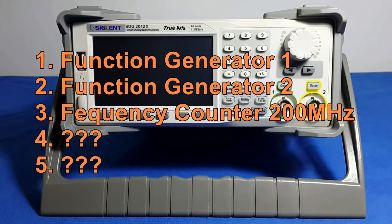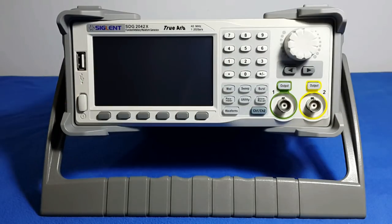To understand my product, I have to go to the datasheet and get some information from it. I need to know what is the minimum voltage I can get in the signal, the maximum voltage, if there is voltage changing between the frequencies. And the most important thing, guys, is the rise and fall times. That means what is the time when one signal goes from zero or from the minimum to the maximum and falls from the maximum to zero or to the minimum.